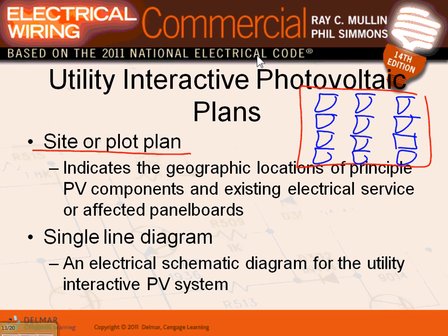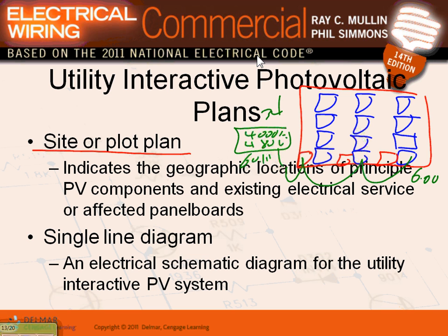And then you're going to show that each one of them is going to have an inverter here. These are all tied together, right? And the output of the inverter, I'm going to take to my grid. I'm going to take this one into my 4,000 amp, 480 volt, 3-phase, 60 hertz system. So I showed all my panels. I'm generating here at 600 volt DC.